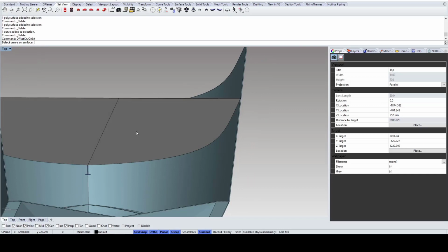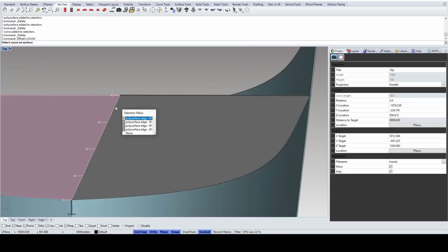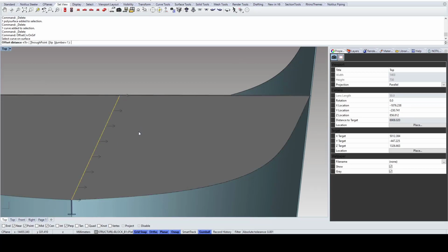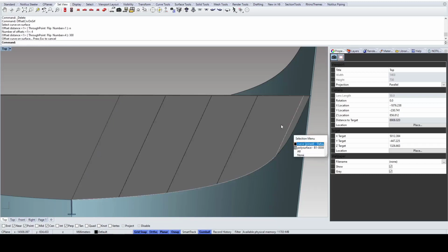For adding stiffeners, users first place the stiffener reference curves. These curves can be created by the offset command or section command. The only requirement for the stiffener curves is they should intersect with the container plate.